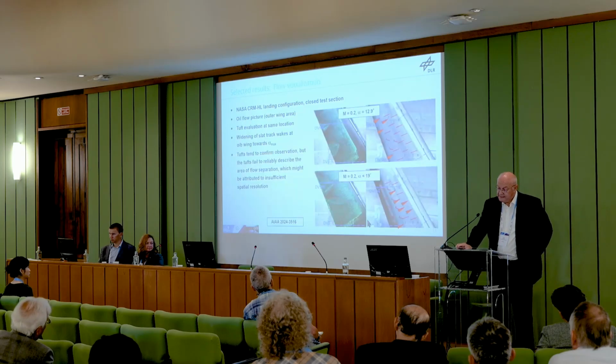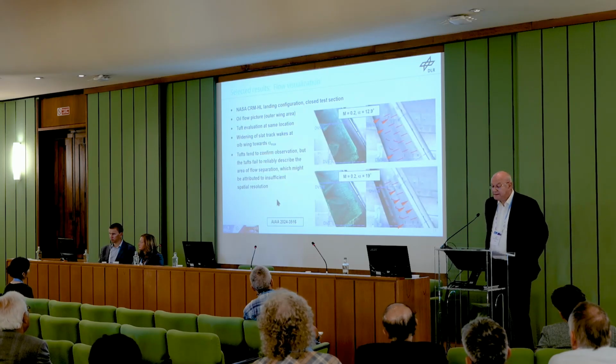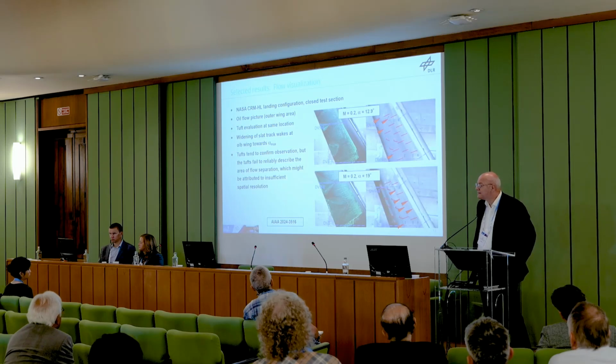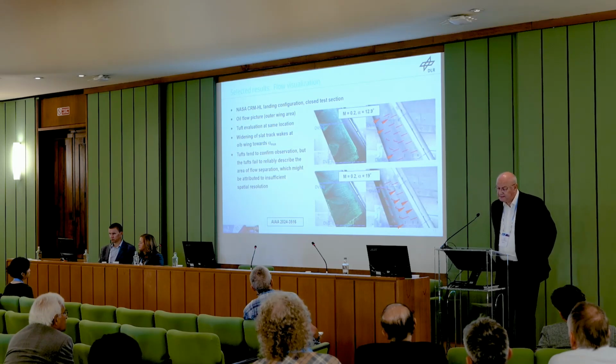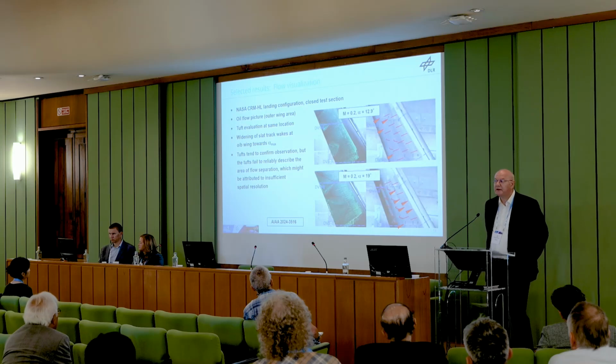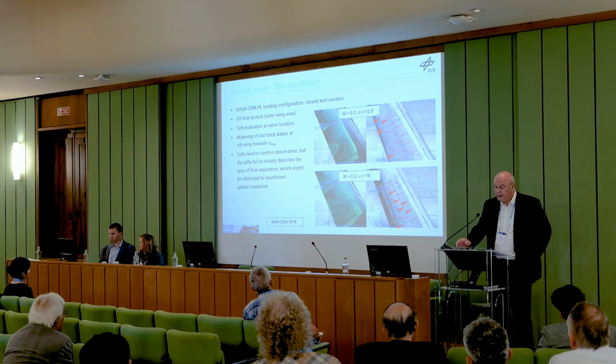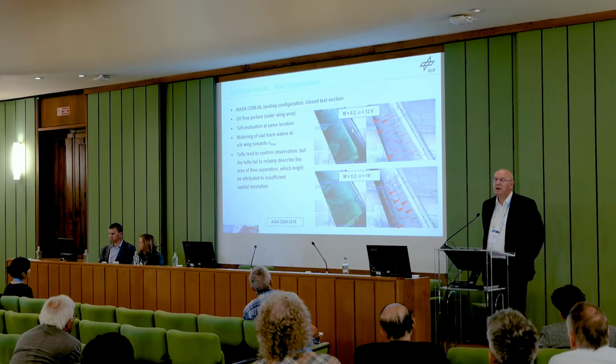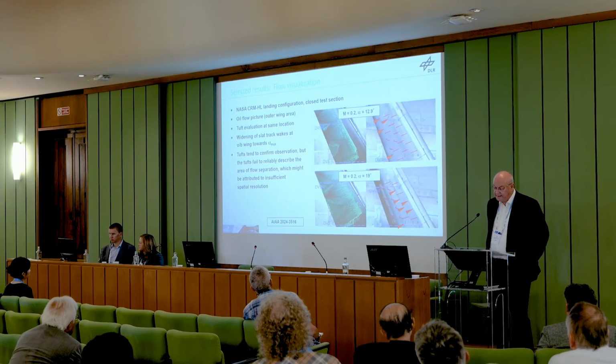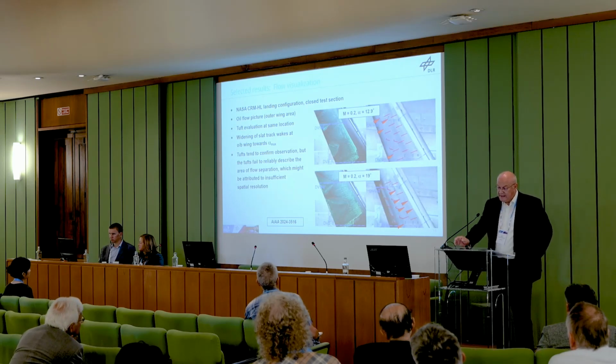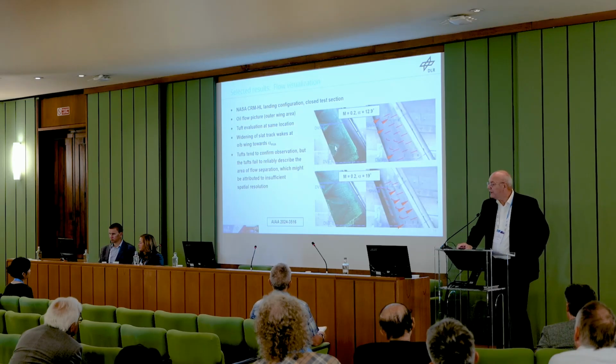All right. Let me come to FlowViz. We all know that the NASA configuration has a distinct trend to separation in slat track wakes. And we did oil flow pictures of the outer wing area. You see on the left the two pictures here, Mach number 0.2, 13 degrees angle of attack, and 19 degrees close to CLmax. The separation areas are indicated by dashed red lines. If you look at that, you can clearly see the widening of these separated areas.